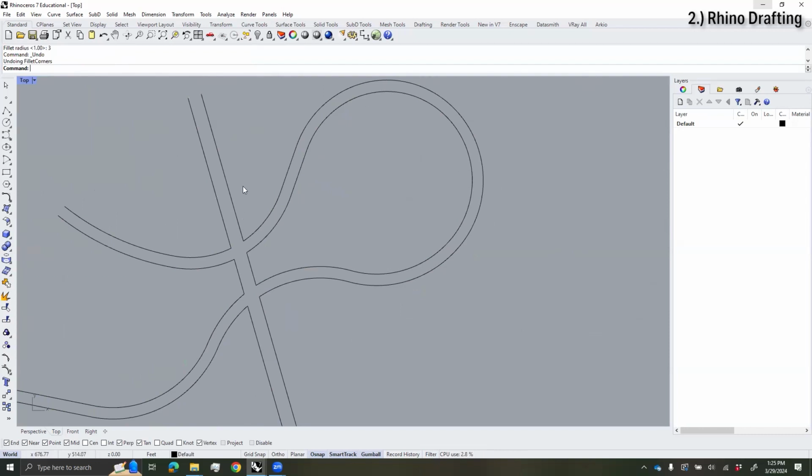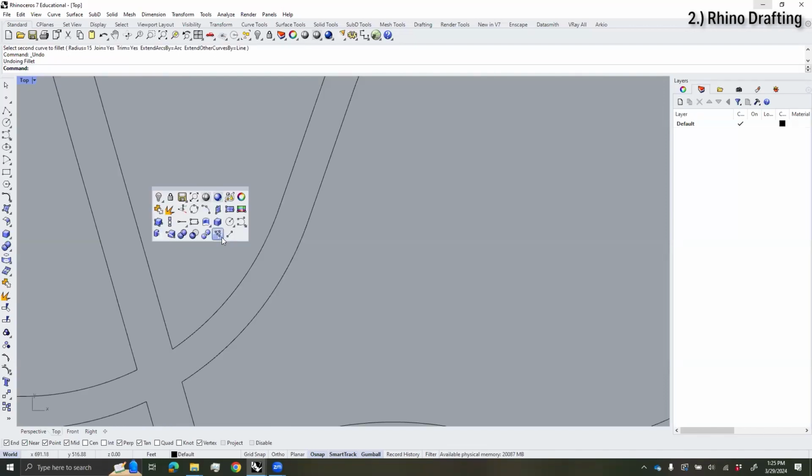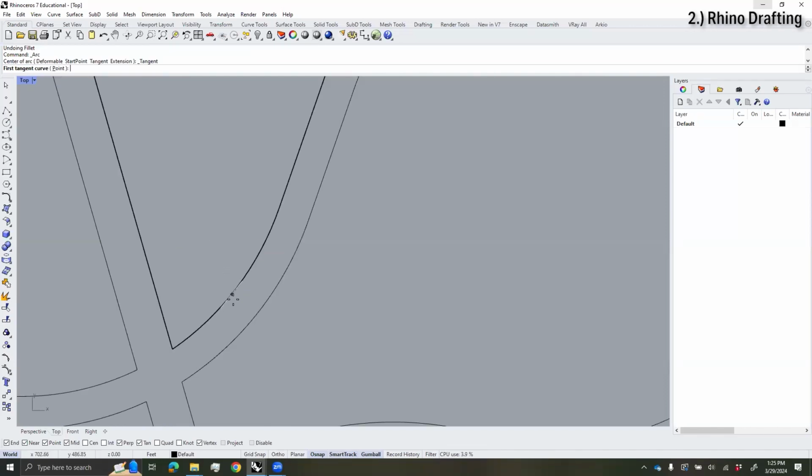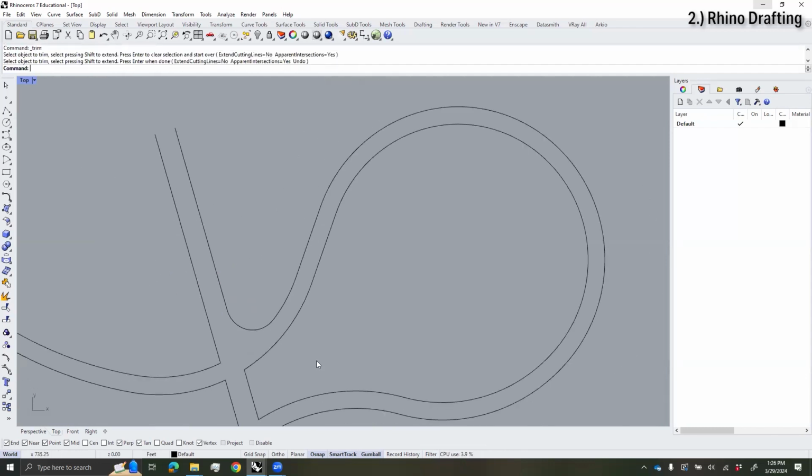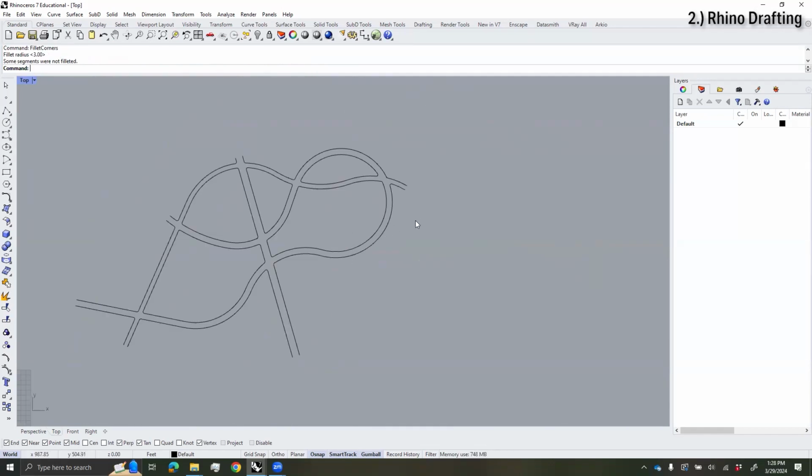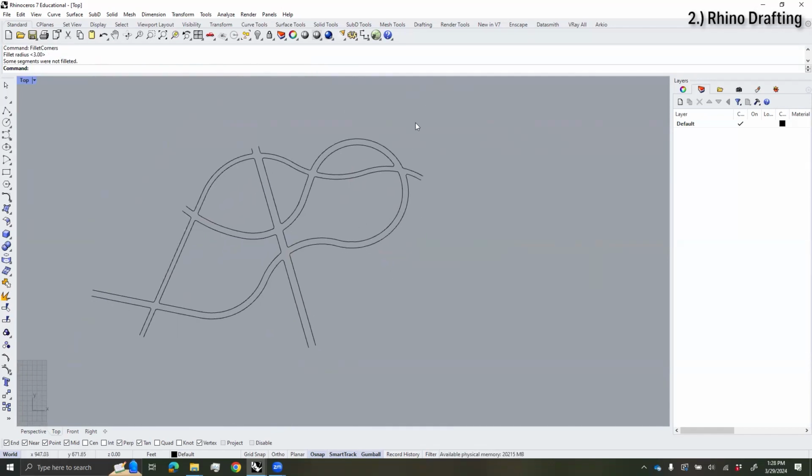Again, I'm going to go back to this arcs tangent to curves tool. You can use that to also fillet curves. So choose arc tangent to curves. And now you just ask yourself, where do I want the fillet to start? I want it to start here. So you kind of look at it and click, all right, I want to start there. Click there, hit F. And now you click and you've drawn that curve, and then just take that and you trim the end there.